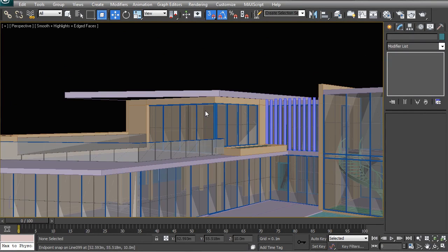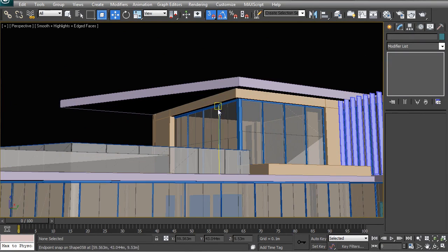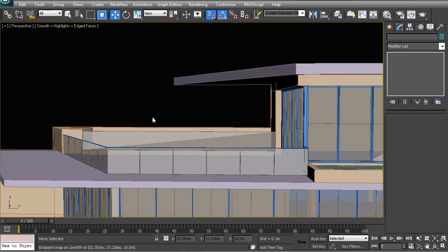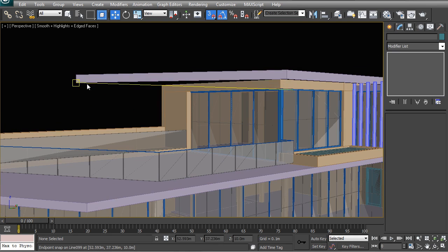Now, the 2 things that I don't like about this right now: the downstand that we have here doesn't really look very elegant, so we want to work out something that eliminates that. Secondly, with the distance that this is cantilevering, it looks like it's at least 4 meters or more. We're going to need a lot more structural depth to make that viable.